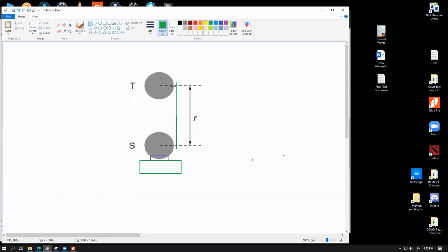So we can place that rectangular block over here, and this hanging cone thing, that top shape thing, can be placed over here, and we can essentially measure that they are equal distance apart. And you can do this in all orientations and on all sides, as many as you want. Actually, measuring it in 4 different sides is good enough, or 3 different sides is also good enough. So you can measure it in 3 or 4 different sides, as long as they're both perfectly aligned. You can essentially make sure they're perfectly vertical to each other.